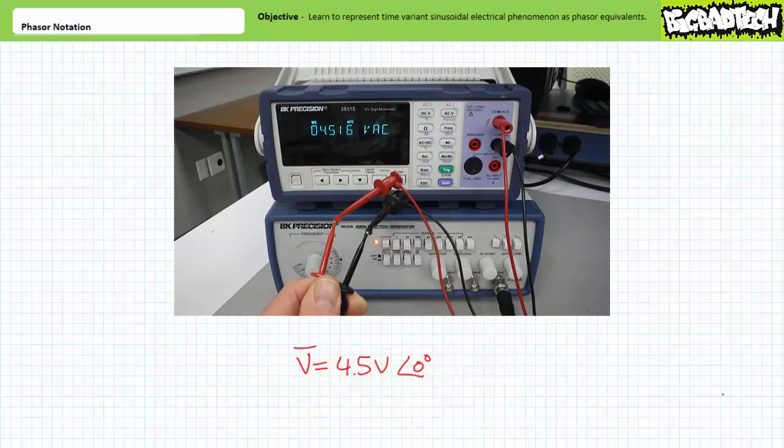Our task could not be any easier as long as you realize all AC voltmeters, all the time, always display effective or RMS voltage unless explicitly stated otherwise. This digital multimeter is displaying an effective or RMS voltage value of roughly 4.5 volts, and it is the reference waveform. The phasor equivalent is therefore 4.5 volts at an angle of 0 degrees.